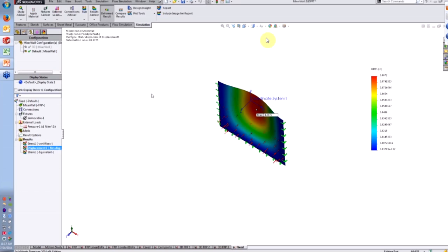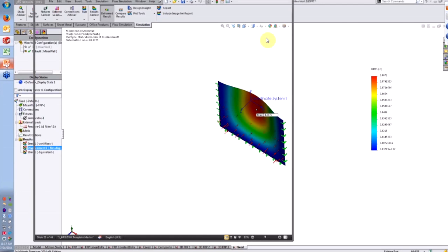So basically, we were able to figure out not only what the true displacement should be in the software by realizing that the hand calculation was making a different assumption. We also realized that if we wanted to continue using that hand calculation, it would be better to use a different formula that assumed the edges were fixed and not simply supported. So again, it's always important to ask yourself what the assumptions of any kind of simulation or calculation method are, and make sure that they match apples to apples.